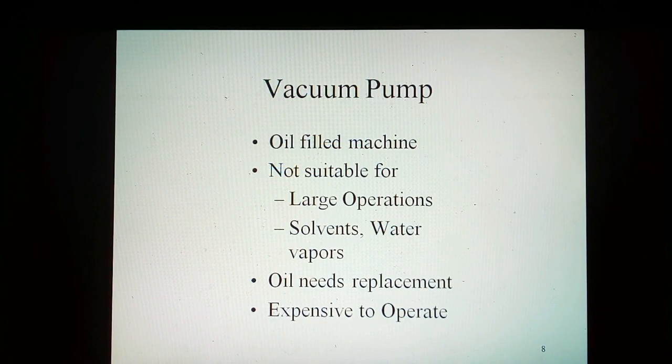In industrial models, or in vacuum pumps of higher capacities which are operated continuously for very long spells of time, the oil gets heated either on account of friction or on account of heavy intake of hot mixture of gas and vapor. The performance of the pump drops. In order to keep it cool, a jacket is constructed around 3 sides of the pump housing, in which water is made to circulate for keeping the temperature of the vacuum pump under control and retaining the performance at its best.